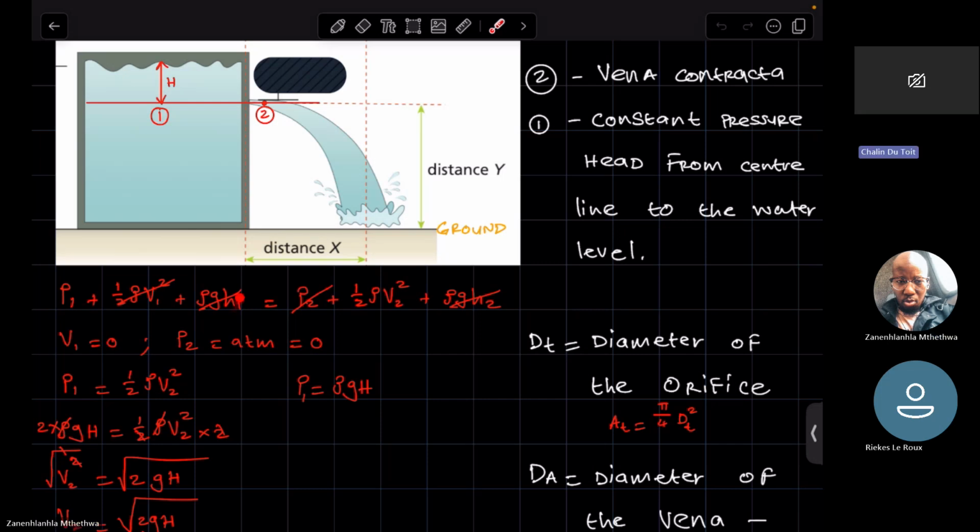So you get a variation that is convenient for calculating pressure, you get a variation of Bernoulli's equation that is convenient for calculating velocity, and you get one that is convenient for calculating height. If you go through that document, you will see exactly what I mean by those three variations. It doesn't matter which variation you use. I showed you those three variations for convenience. I find it best to use the variation of Bernoulli's equation based on what it is that you are looking for. If you're looking for pressure, this is the one I prefer using, because you don't have to do too much manipulation. And then you get one for velocity, and one for height as well.